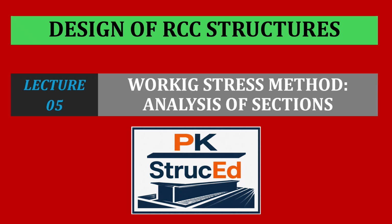So what is analysis? In case of RCC, analysis means finding the moment of resistance, or finding the safe load a given section can carry without causing any failure, or estimating the stresses developed in concrete as well as in steel. We will understand this concept through three numerical problems that we are going to discuss in this lecture, each highlighting a different behavior of RCC sections.